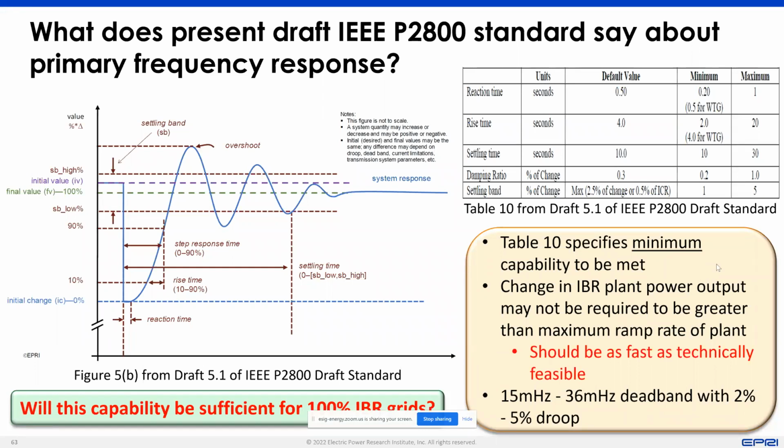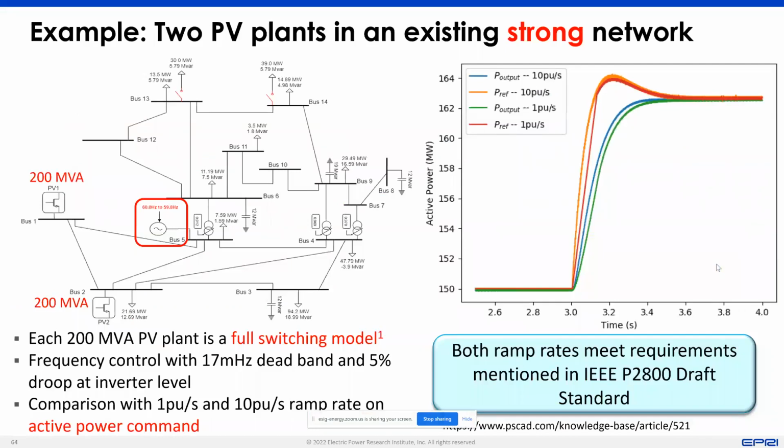And this becomes important when we are especially considering things like the ramp rate behavior of a plant. So a battery energy storage system may have the capability to have a higher ramp rate as opposed to, let's say, a wind energy system because of the mechanical constraints that are involved in the wind energy resource. So taking into consideration that ramp rate capability in providing the service to the system in terms of frequency response is important, especially if you consider the number of resources that are to be involved in this responsive behavior.